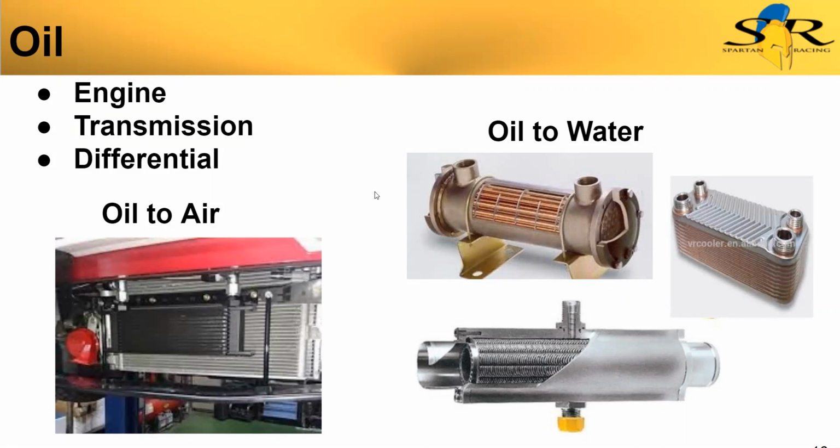I'm sorry, say that again. I missed the last part. Basically add an oil cooler, but put coolant rather than oil through it, and then have a radiator for the oil cooler. Oh, okay. Yeah, you could do that. That would just be like an intermediate heat exchanger.